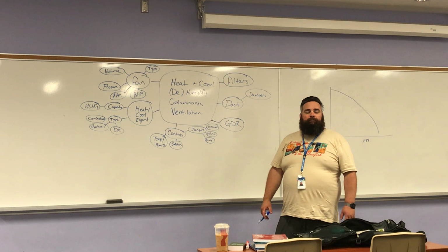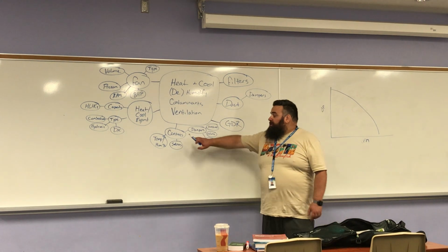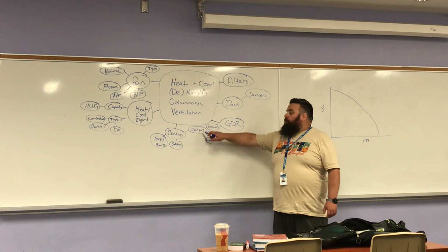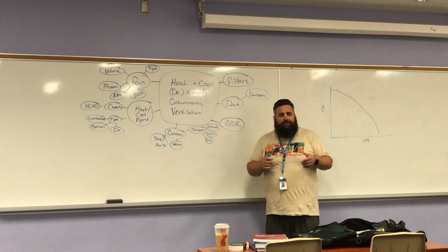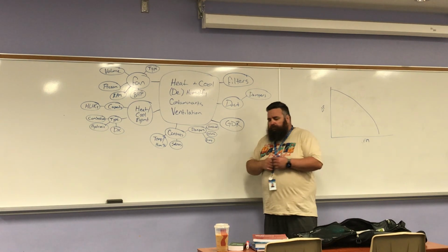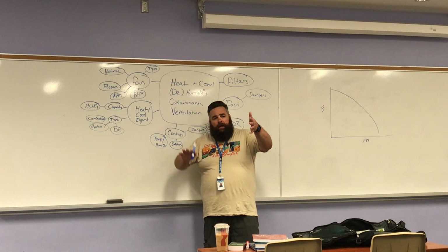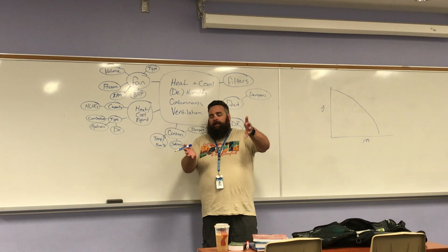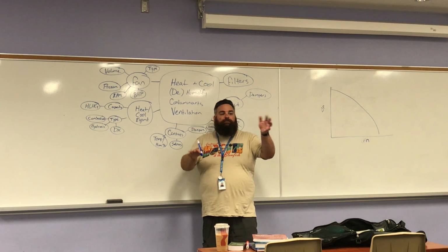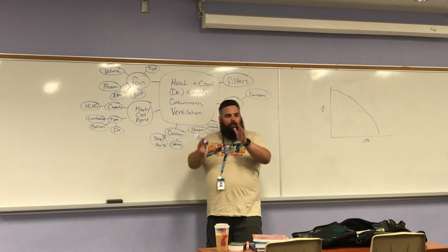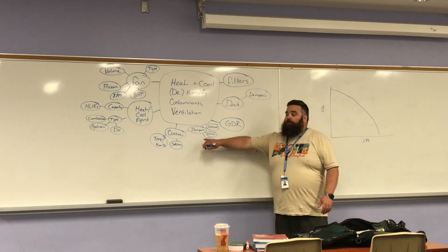Can controls also manage mixing? Controls definitely can manage mixing. That would incorporate dampers. Are you familiar with an economizer on a rooftop unit? An economizer will typically have the economizer damper and a return air damper, and it will regulate that to get more from the economizer outdoor air versus less from the return, or more. And that actually gets really interesting when you're trying to coordinate.